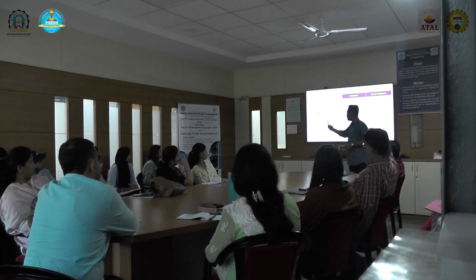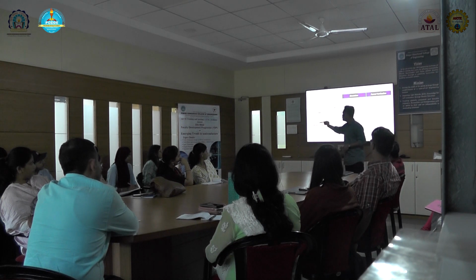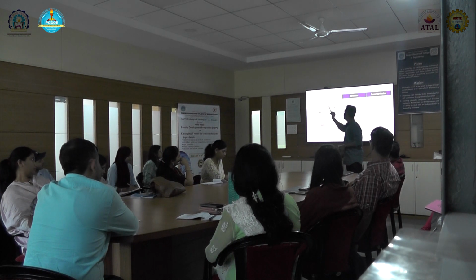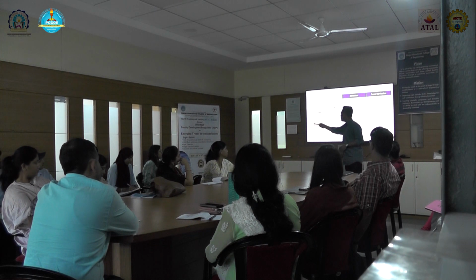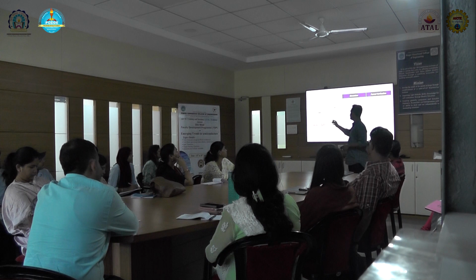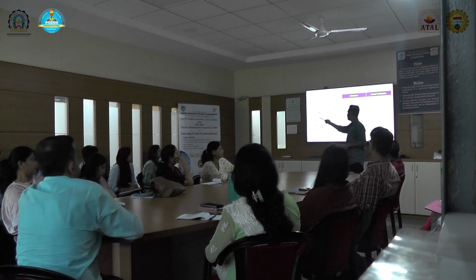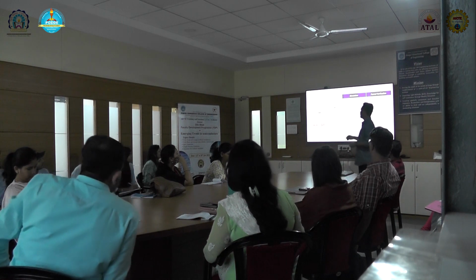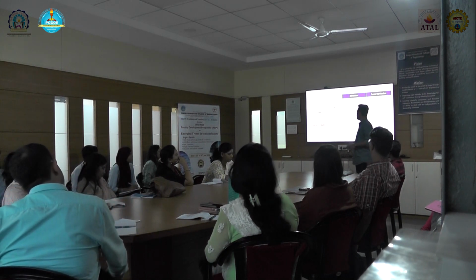You can see the graph here. The red one indicates the simulation, where the setup time is high and it takes some time to develop the test cases, whereas in formal, the green one, we can set up early and find the bugs as early as possible. So formal enables a shift-left focus. Less setup time is required and we can find as many early bugs as possible.